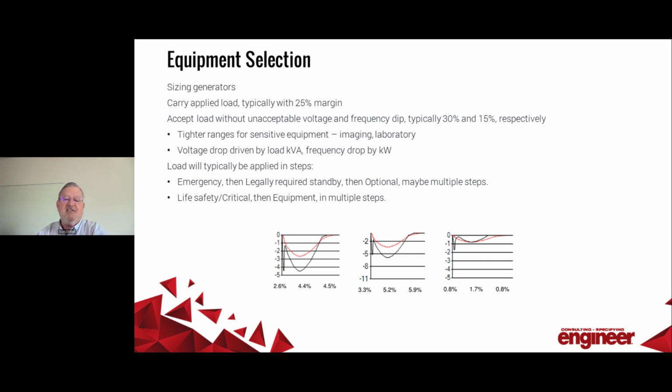Loads are typically applied in steps. Emergency loads will come on within 10 seconds, legally required standby in 60, and optional loads come on at leisure. Lower priority loads often have a substantial HVAC component, so they can be very large. And so often you'll see that the optional loads are staged on in multiple steps.